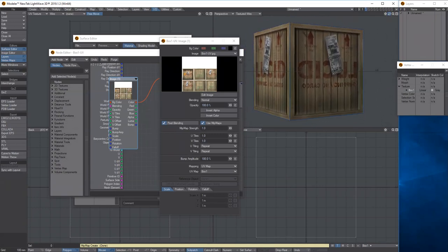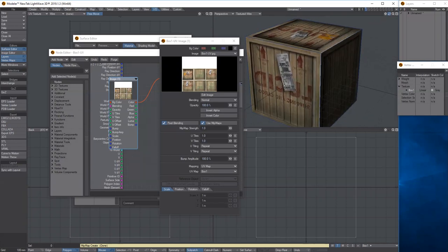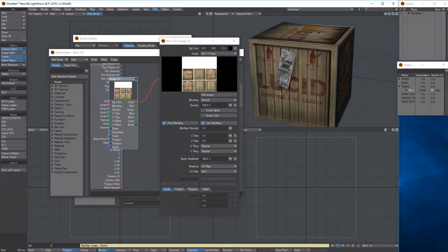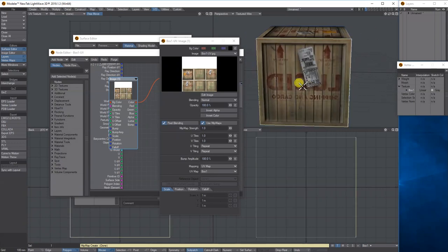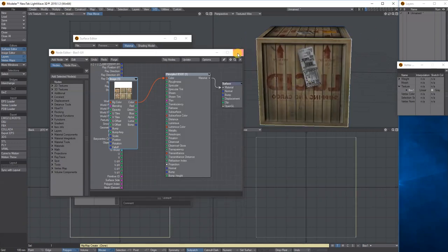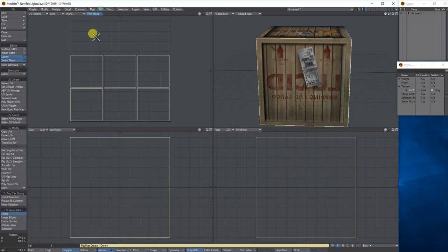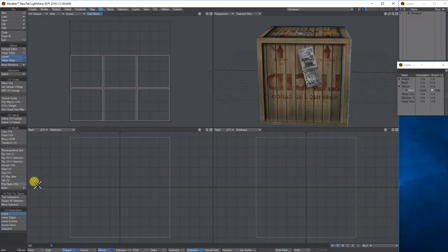Now as I'm looking at it, like I said, I'm not particularly bothered which size is which, you can change these around in Photoshop and just update it, but I've noticed that this one here is facing the wrong way. So if you get that on your map and it's facing the wrong way, click on it, go to the UV map, and down the side here you've got different flip options.